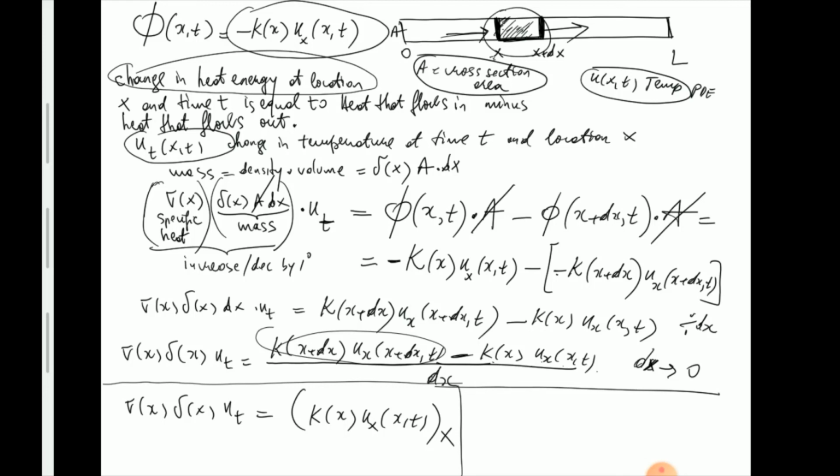What's left on the left side are just physical constants involved in that process, specific heat, density, and so on. The right-hand side expresses the same thing, but as energy coming in and out of that unit of volume. That happens to be a derivative with respect to x of the product between the conduction term, k(x), and the temperature gradient, u partial x.